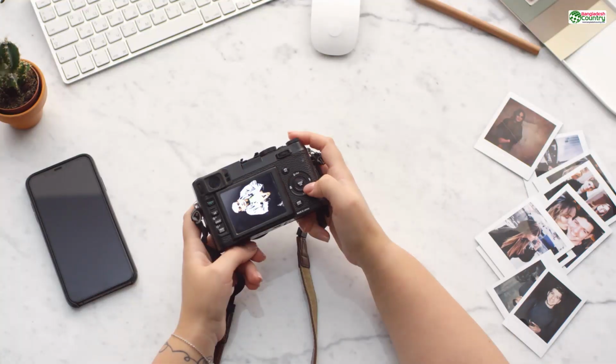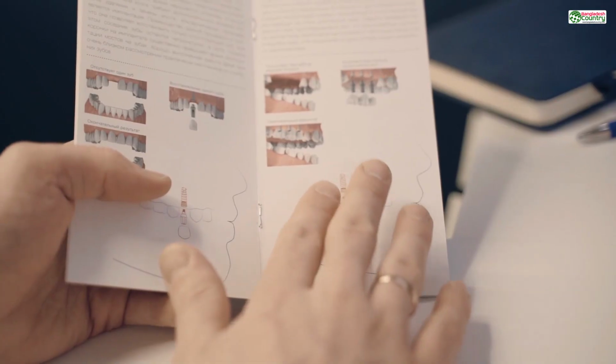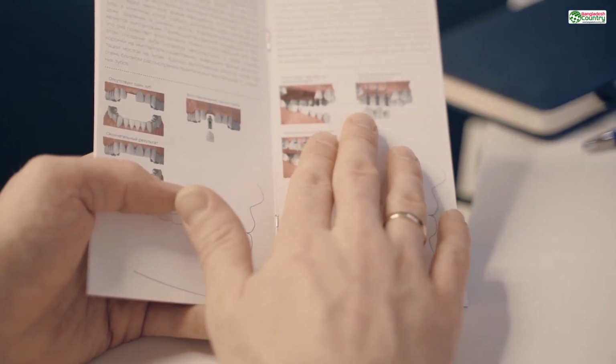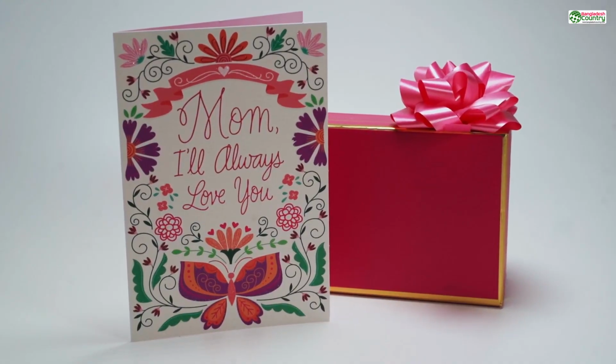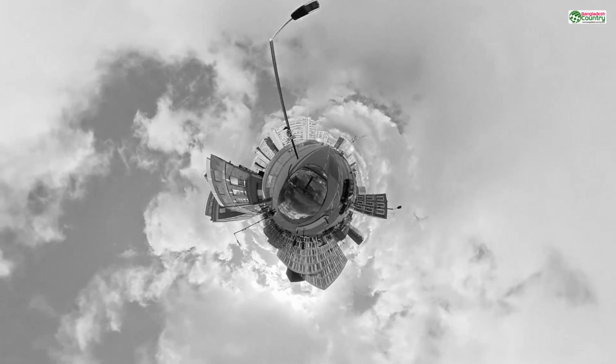For example, if the guide says the minimum wall thickness for their PA12 nylon is 0.8 mm, I'll design my part with a 1.5 mm wall. It adds a tiny bit to the cost but provides a huge amount of extra strength and peace of mind. It's the cheap insurance that guarantees my part survives the journey.